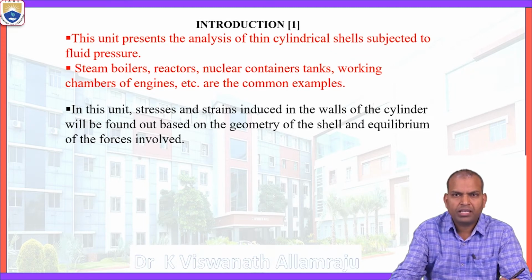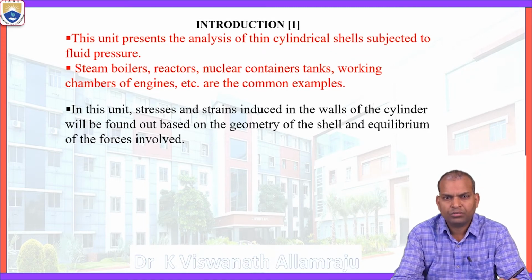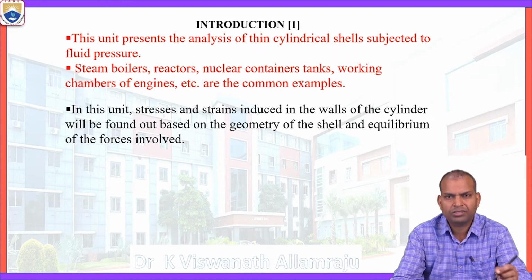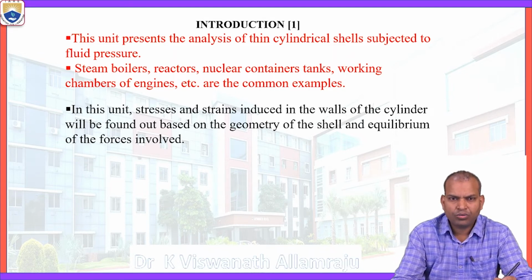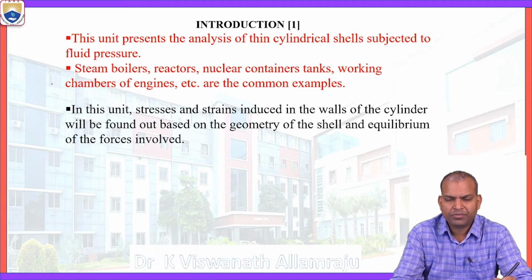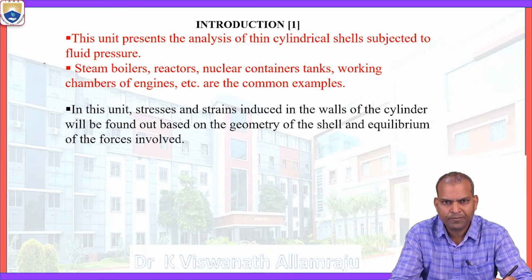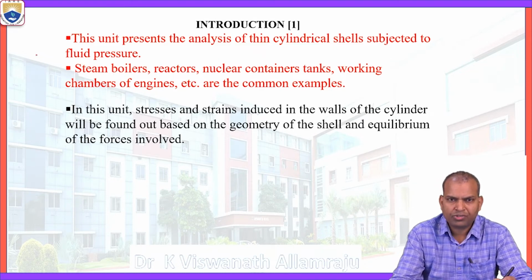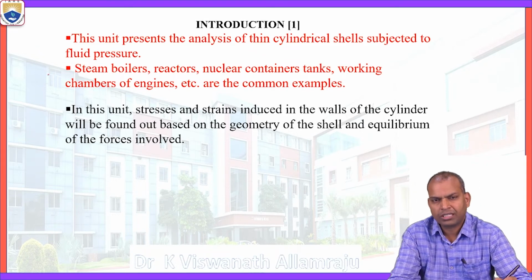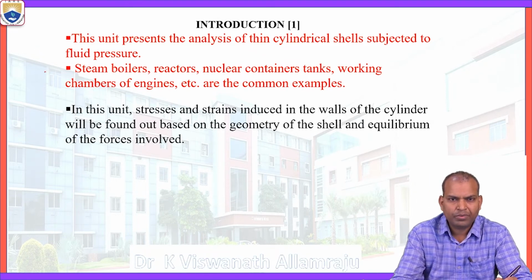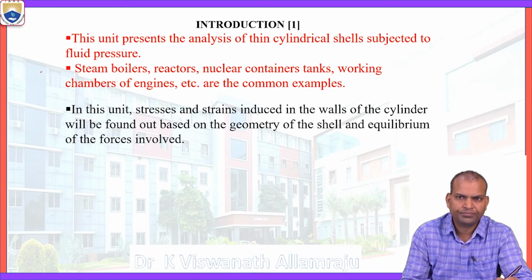What we are going to study in this module is the stresses and strains developed on the thin walls of the cylindrical shells, and how these stresses are developed. There are various types of normal stresses, such as hoop stress and longitudinal stress. And what about strains, such as volumetric strain, longitudinal strain, and circumferential strain? How are they developed when fluid pressure acts within the cylindrical shell or spherical shell?